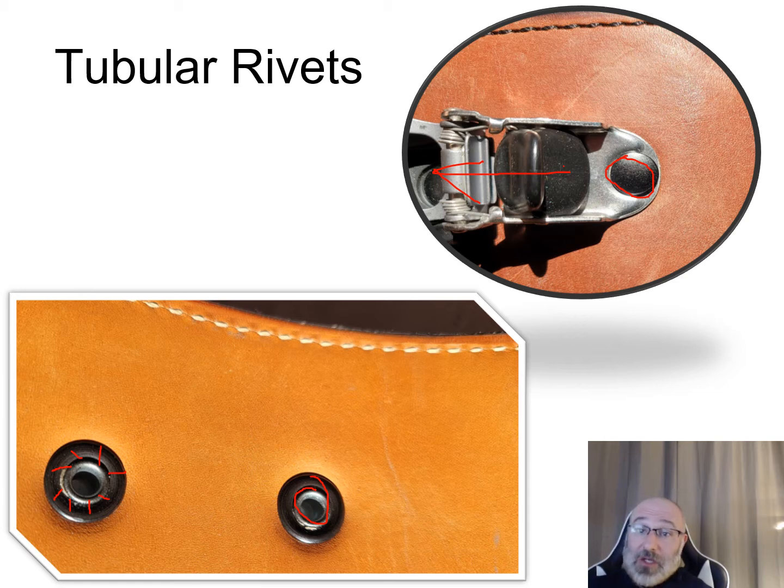But what that can do is elongate the hole and deform the hole in my leather. And if the hole in my leather deforms a little bit as that stretches and stretches, I need to make sure that this washer is going to be big enough so even if the hole deforms, it's not going to pull through the leather. So again, different applications, we need to think of different types of rivets that we could use.